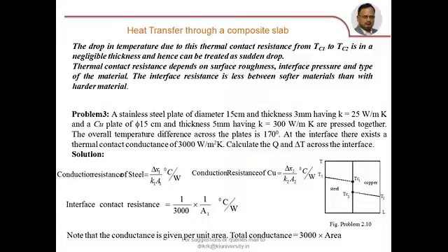Similarly, when you are joining two different materials, to avoid this thermal contact resistance, in between the two surfaces, you can think of adding some soft material or adding some greases, like silicon grease substances like that, which will fill the gap and have better conductivity than the air. So these are all certain techniques to reduce the thermal contact resistance between the surfaces.